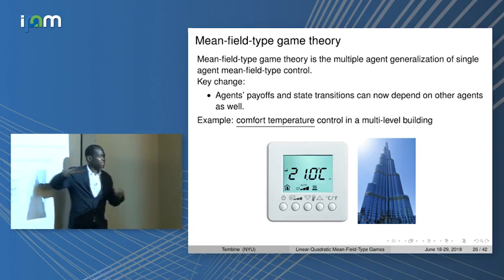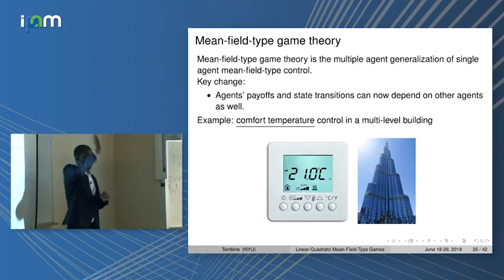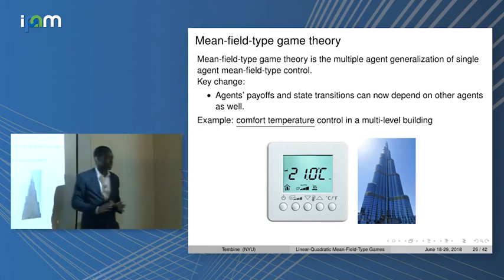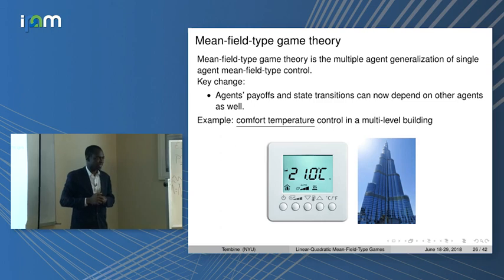So if you go in a place where you look at the air conditioning, it's trying to look at the variation, right? I start cooling when I see that it's going out of that. I start cooling because it's exceeding the upper bound, and I start heating if it's exceeding the lower bound, right? So you design the control such that you stay in that box all the time. Maintain the temperature in the comfort zone all the time. This is what you want to do.